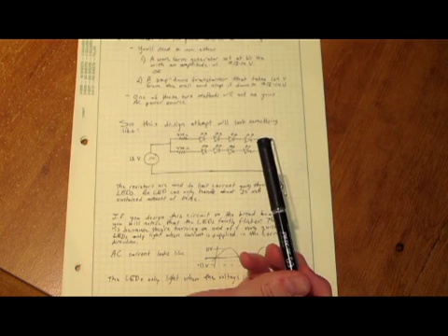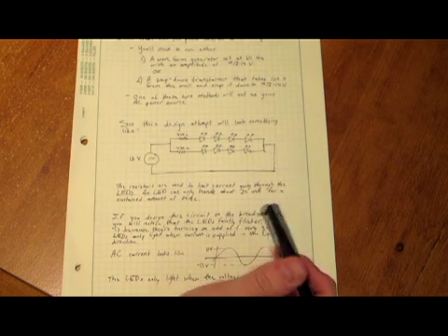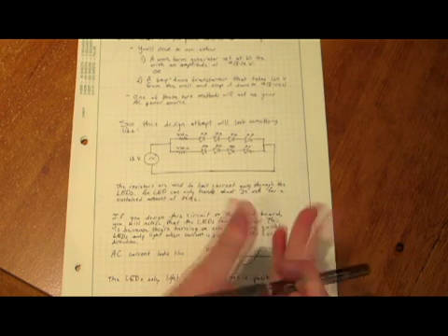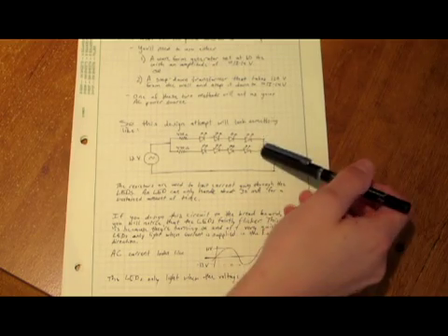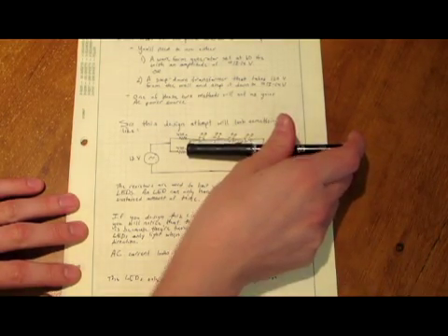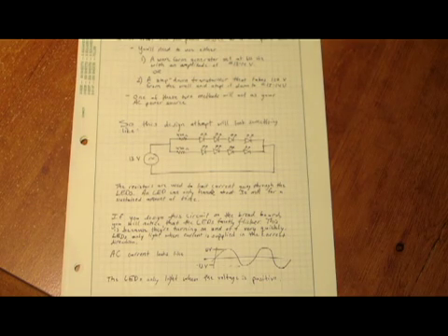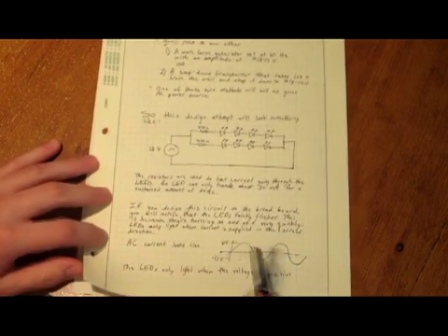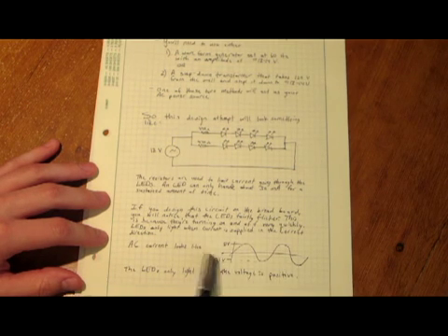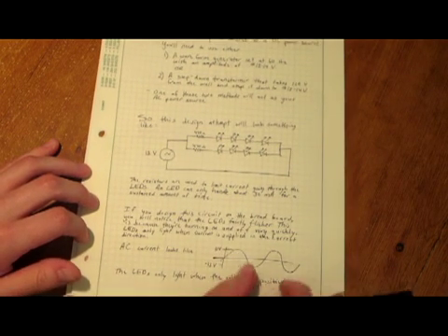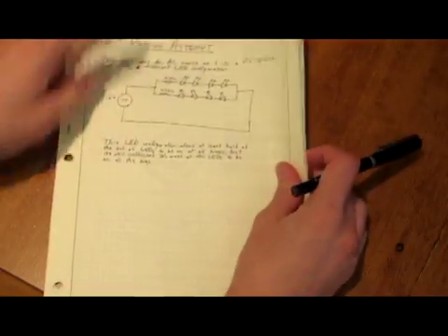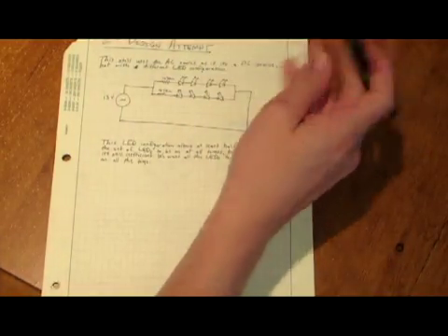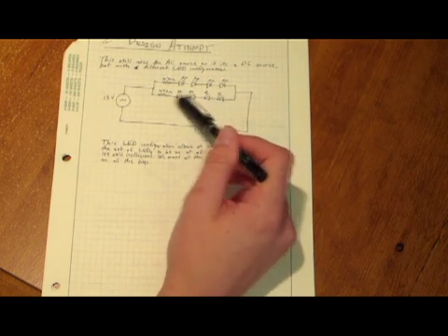And that's because all your LEDs are only on for half of the time because of the alternating current. Sometimes the current's going to be going in the negative direction, and LEDs are diodes, obviously, so when current goes back through them the wrong way, nothing happens, or they might blow up if it's too high of a current. And that's kind of the graph of what alternating current looks like, and that's the reason that they're only on half the time.